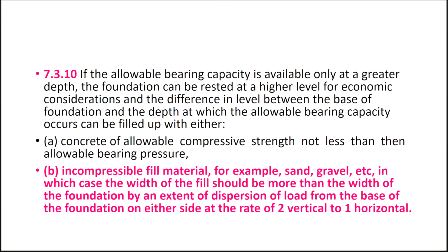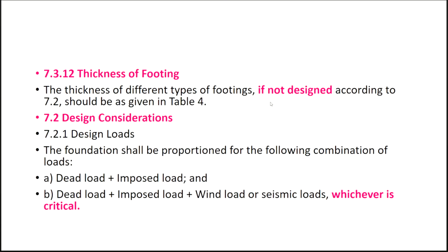Suppose you have 2 meter depth of foundation, but you have a soft strata or a layer which is having a soft soil which may be at 4 meters down. Yes sir. So how the load dispersion will go, for how much load, that calculation he will be doing for the settlement of that particular soft strata. He is trying to tell you how it will be there for that case.